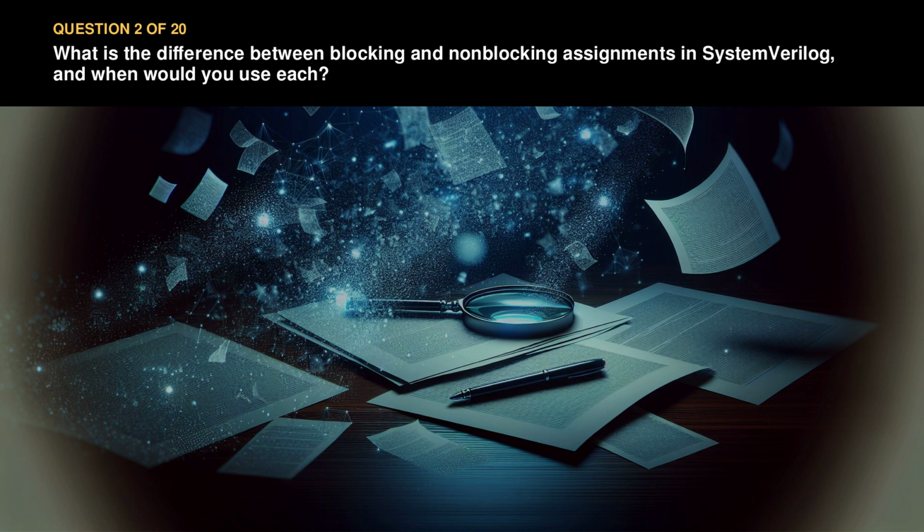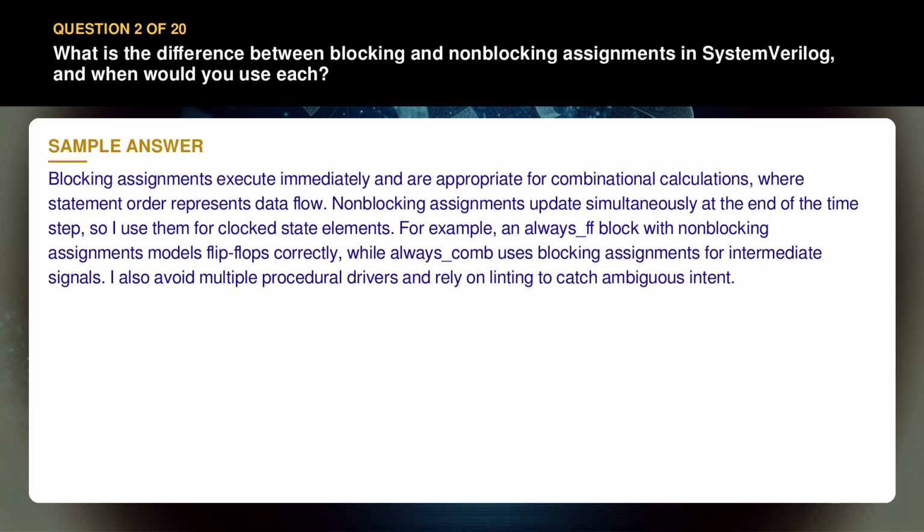Question 2. What is the difference between blocking and non-blocking assignments in SystemVerilog, and when would you use each? Blocking assignments execute immediately and are appropriate for combinational calculations, where statement order represents data flow. Non-blocking assignments update simultaneously at the end of the time step, so I use them for clocked state elements.